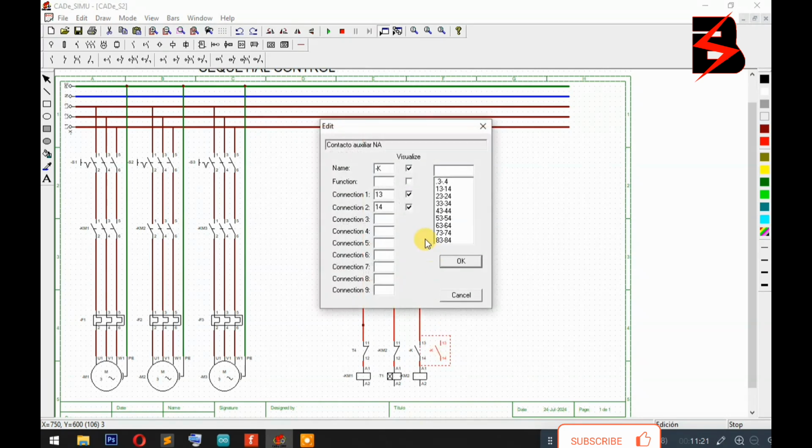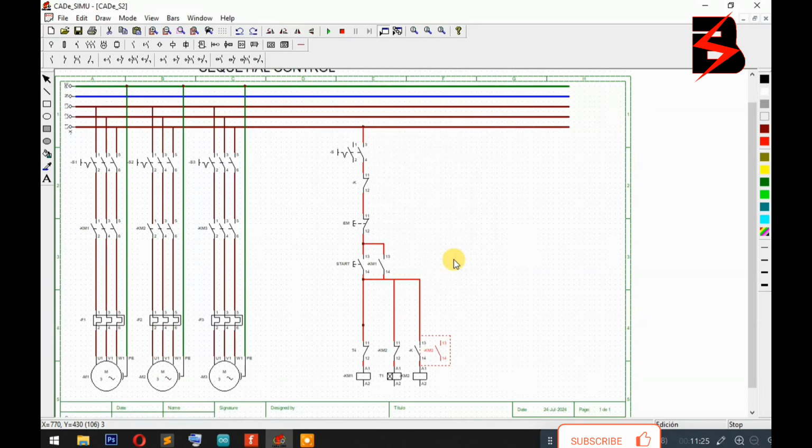Yes, so this is KM2 as well. Because I'm designing in a way that once timer 1 powers contactor 2, it has to go off and leave contactor 2 alone. So contactor 2 has to self hold itself, and that is the logic.